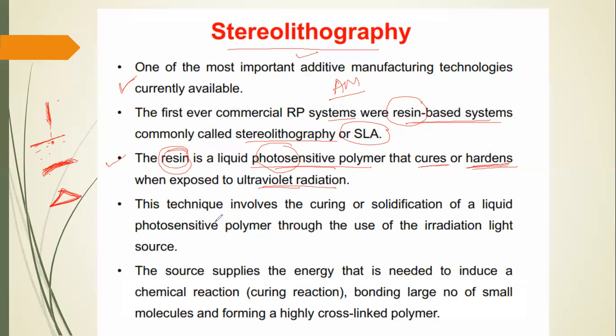This technique involves the curing and solidification of the photosensitive polymer through the use of an irradiation light source. So radiation, commonly ultraviolet, is used in order to make this curing, converting the liquid into a solid. If you want to get the 3D component, it should be a solid.